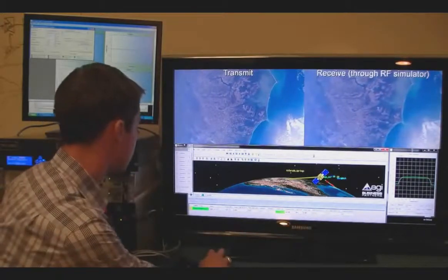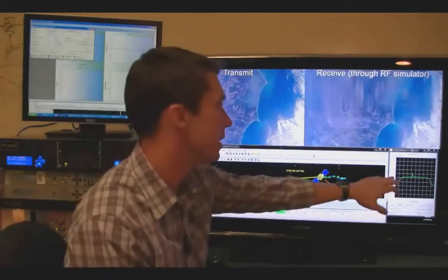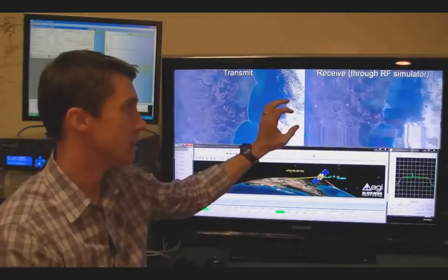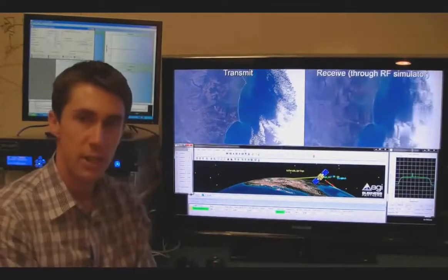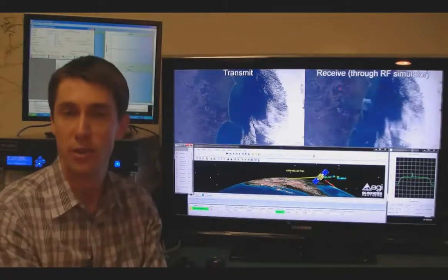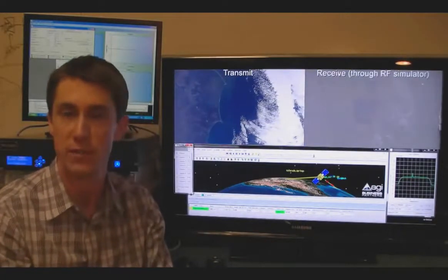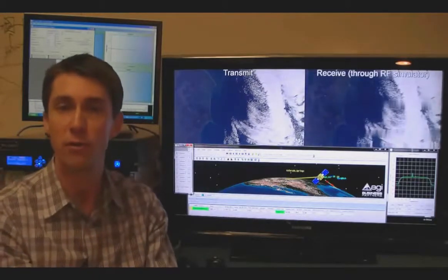And finally, I'll inject several interfering signals underneath our primary carrier, and it distorts the data again. The quality of service is significantly degraded. So the RT Logic channel simulator provides a realistic way to test RF communication equipment, be that modems, transmitters, receivers, software, firmware, and this can all be done in the lab before flying a mission.